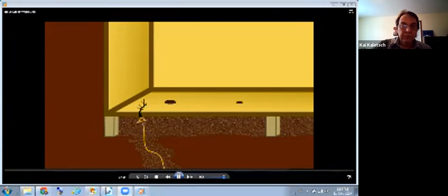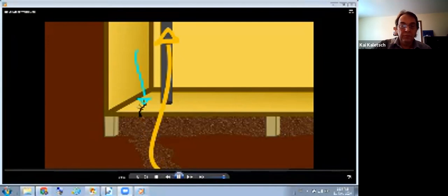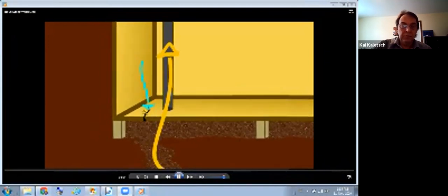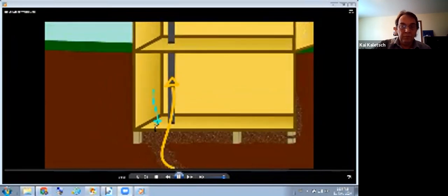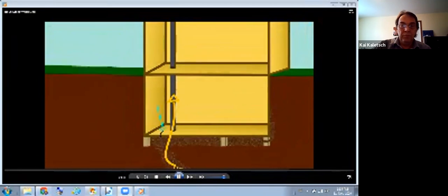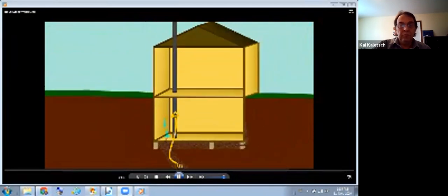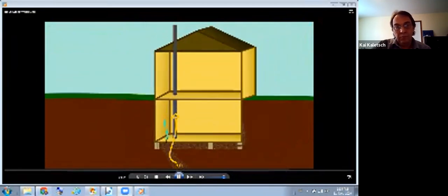Then the mitigation system would be put where most of the source is, or at least where there is good communication with the source. Therefore, the radon will be moved directly, without first being dragged all over the underside of the slab. Because a test point is close to the radon source crack, the likeliness of not having enough suction to maintain the airflow in the right direction is much less. There also isn't a waste of suction bringing in clean air from the outside.